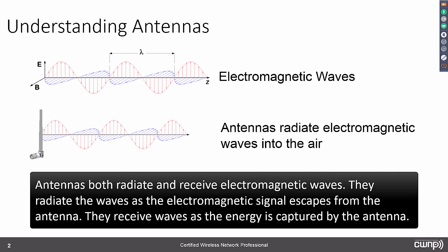And it is those components that are intelligent. It's those components that make a decision as to whether this is a signal or if it's just some type of energy that is in the space, maybe from an unintentional radiator or from an intentional radiator that is not compatible with that particular radio. So the point is that antennas don't make decisions. They just do what physics dictates that they do. That's the first step to understanding antennas.